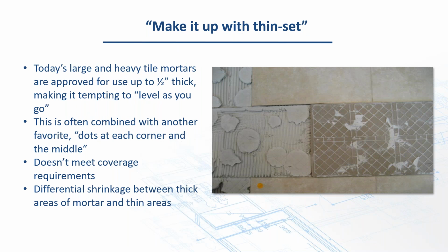What happens when you don't prep? Well, this is one of the things we see commonly when they don't want to do proper prep. They do spot bonding, where they just take blobs of mortar and stick it up there and kind of beat it into the tile next to it till they all look fairly level. Problem is it's a weak bond. Thin sets aren't intended to be used that way. They fail commonly, very commonly. It's just a matter of when, not how.